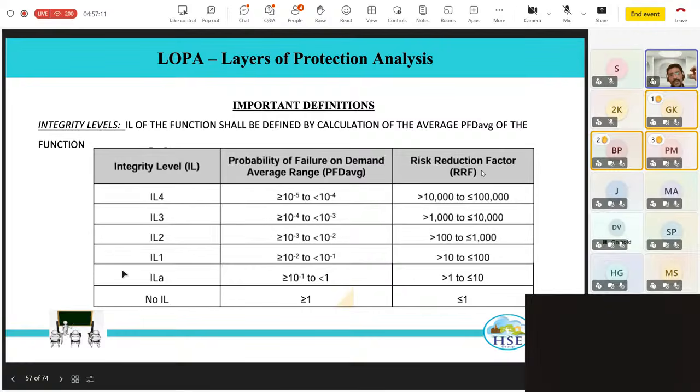Revisit the design and try to reach the ALARP region through design changes rather than going for a higher SIL level. The rationale is that whenever you go from one SIL to another SIL, the cost increases by 25%. So imagine, you have a 25% cost increase here, then you have a 25% here. So basically you are having a 100% cost increase across these levels. That means where your plant was supposed to be 5 million, it is already inflating your cost by 100%.